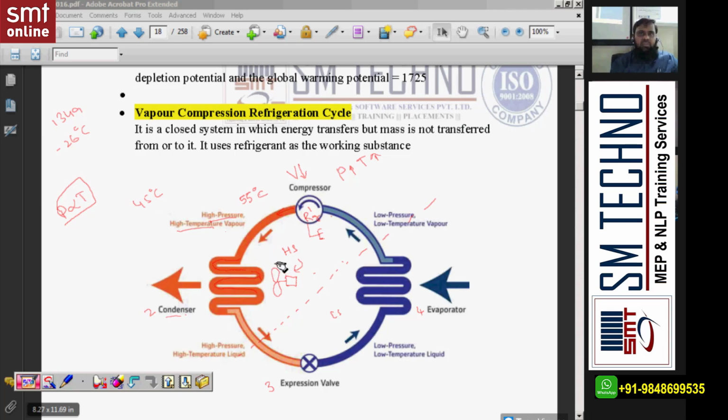So as per the second law of thermodynamics, heat transfers from high to low. So what happened when the air is thrown on the coil, the refrigerant heat will be extracted by the air and the air comes out as hot air, and this condenser is designed by the manufacturer to pick the heat equal to what? Equal to latent heat.